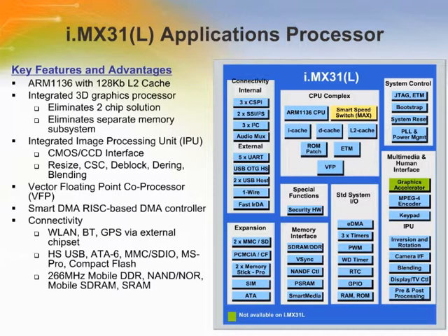The LCD controller, supporting up to SVGA displays, and the MPEG-4 encoder, supporting up to 30 frames per second, are just some of the reasons why this device has been so prominent in the multimedia space. Combine the performance of the i.MX31 with its high degree of connectivity, including the USB OTG, and the i.MX31 becomes appropriate for a wide variety of applications.